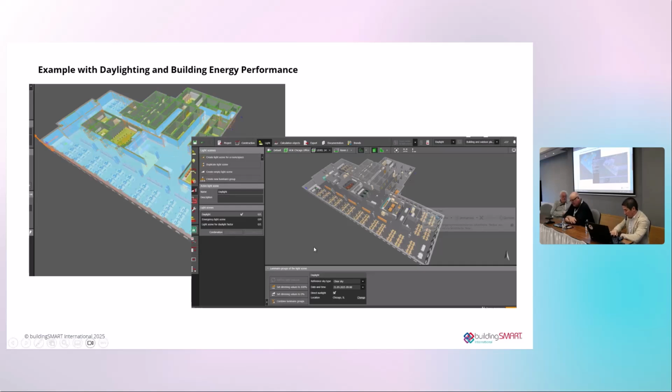In order to do that, you can run simulations and provide that simulation. In that case, we use, as you can see, Chicago. I didn't change anything. I simply used the model geolocated directly from the IFC model. So I imported it and it directly recognized where the building is. I only had to change settings for the daylight simulation that, according to the standard, you have to run. As you can see, we did it for September 21st at 9 a.m. and you have to do it at 3 p.m. as well. So we run it and it directly shows you results if you meet the requirements for daylight.